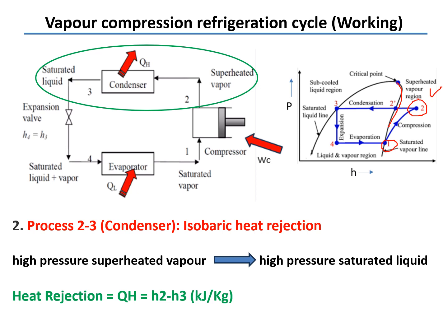So here inside, this is the wet condition of the refrigerant. There is a wet plus vapor region, and the right side becomes superheated. So 2 is a superheated condition of the refrigerant. Here, this is the discharge side of the compressor. Now in the condenser, the heat rejection will take place. So here at 2, the enthalpy is H2, as I already told you.